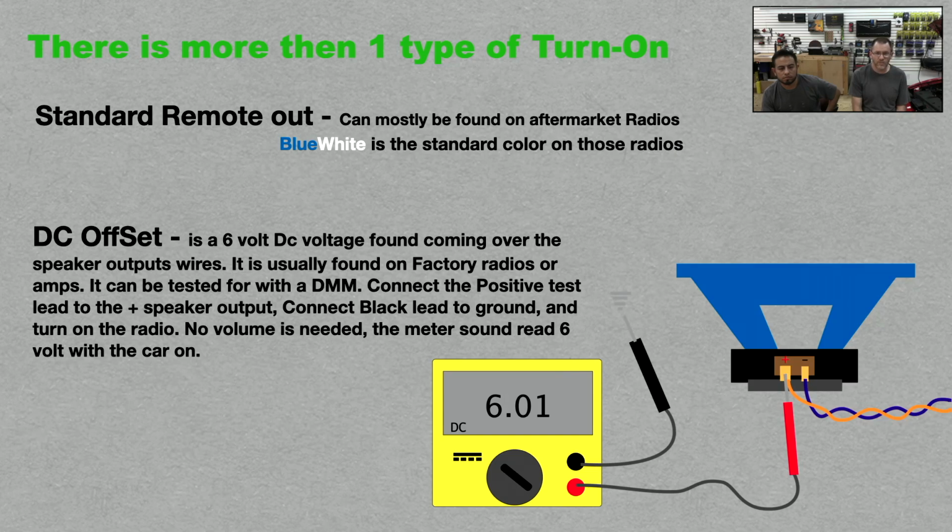Turn the car off, wait for it to go to sleep, make sure it goes away. It may not turn on and off with the car because the car's stereo, though the screen will go off, that does not mean that the back side of it, meaning the amplifiers and whatnot, are actually turning off. A lot of times when you turn off a modern car, all it's doing is turning off the screen. It is not actually turning off the stereo because there are chimes and or it takes a long time to boot up. So they are doing a staggered shutdown so that everything just doesn't go boom, off, speaker pop.